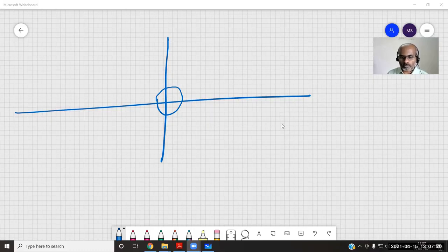In the Laplace transform, step input was used for the stability checking. Now we are using frequency input. This dead time system we can approximate with a polynomial, but that is still only approximate. Instead, this Bode plot is very rigorous and much more useful for the stability studies.